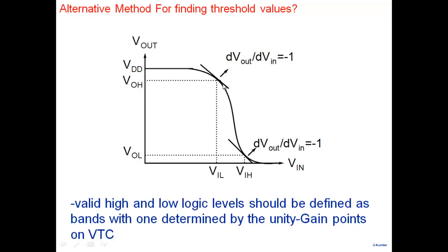Why are they saying -1? So one has to prove that. What we are talking about, you have to take a range of voltages here. And we said, how low can I go to VOH? Well, they said, you should go to VOH as low as to a point where the slope is -1. If you go beyond that, they say noise margin will begin to decrease.